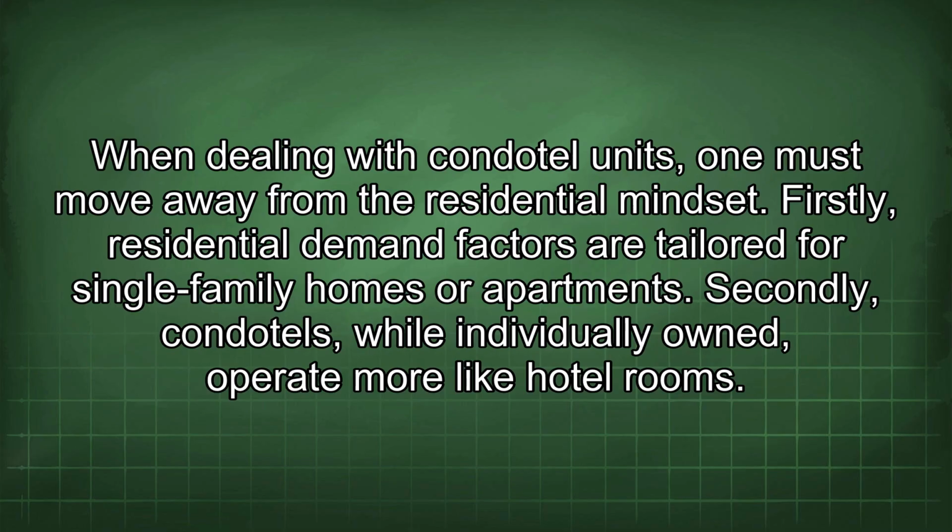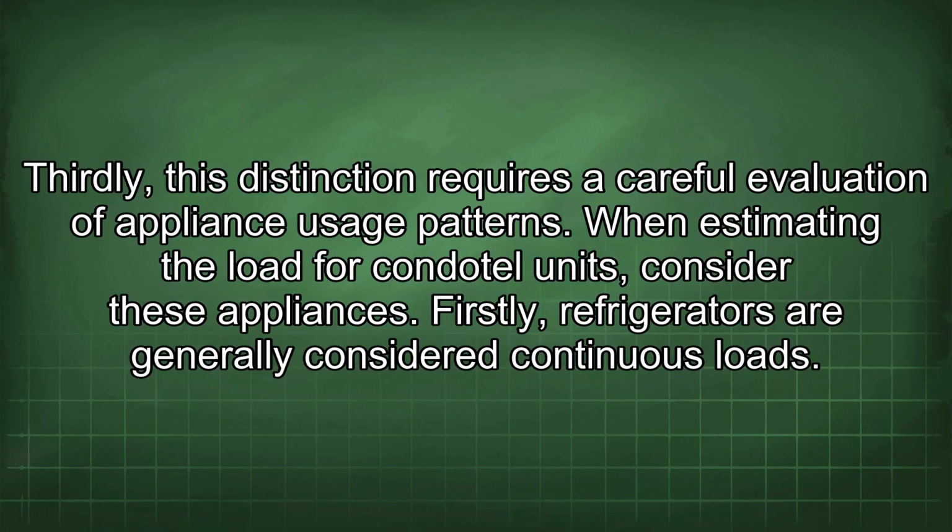When dealing with Condotel units, one must move away from the residential mindset. Firstly, residential demand factors are tailored for single-family homes or apartments. Secondly, Condotels, while individually owned, operate more like hotel rooms. Thirdly, this distinction requires a careful evaluation of appliance usage patterns.